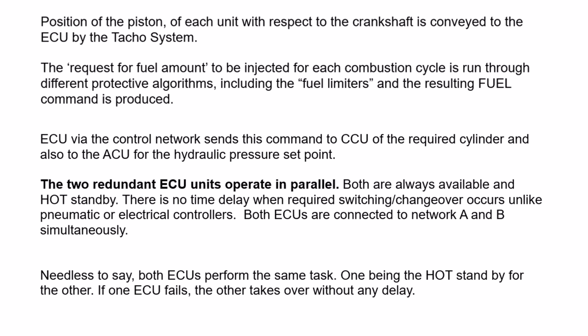The request for fuel amount to be injected for each combustion cycle is run through different protective algorithms, including the fuel limiters, and the requesting fuel command is then produced. What is a fuel limiter? Remember the camshaft fuel limiter? All ships have that. We'll talk about it in a while. Other limiters are what we have on these ME engines, electronic engines. The ECU via the control network sends this command to the CCU of the required cylinder and also to the ACU for the hydraulic pressure set point.